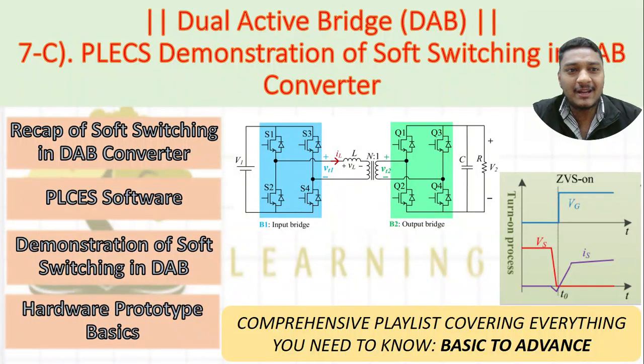In the last two classes you might have seen that we have discussed the soft switching concept, how exactly soft switching happens in any converter. Then we started discussing exactly how the DAB converter experiences soft switching, when it happens in the DAB converter. Then we discussed the voltage ratio constant m, right? For m greater than 1, in which particular bridge are we going to get soft switching? For m less than 1, in which bridge are we going to get soft switching?